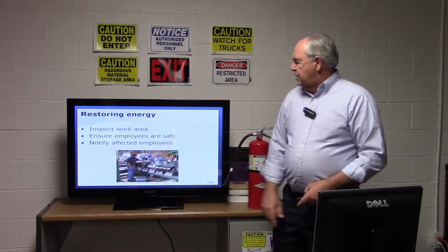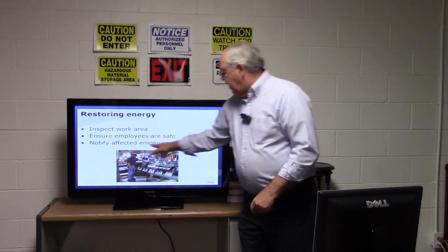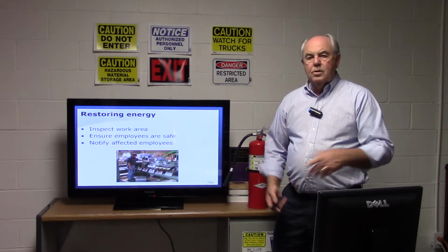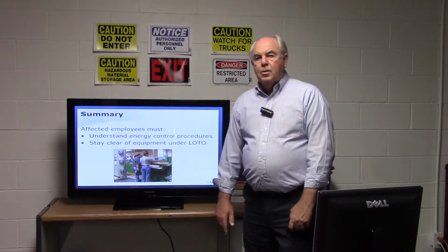Ensure the employees are safe. Make sure that they know you're about to start this machine back up. Notify the affected employees and look around you and start the machine back up. You should be about ready to go back into production.